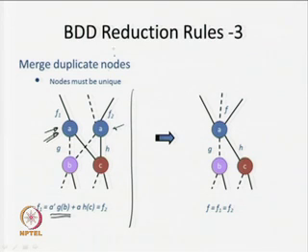Similarly, I am coming to this particular node, and whatever we have evaluated over here is say F 2. Now, again you just see that when A is equal to 0, we are coming to the same node B, and we are going to look for the same function G, and when A equal to 1 we are coming to the same function H. So, in this particular case the partial evaluation of the given function for F1 and F2 both these functions are same. So, we are saying that F1 equal to F2 which is your A dash GB plus A HC.